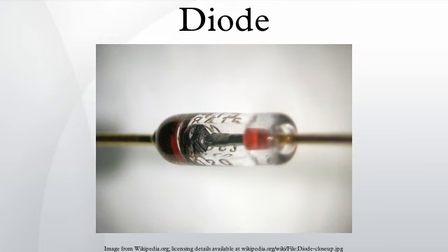Gunn diodes. These are similar to tunnel diodes in that they are made of materials such as GaAs or InP that exhibit a region of negative differential resistance. With appropriate biasing, dipole domains form and travel across the diode, allowing high-frequency microwave oscillators to be built.